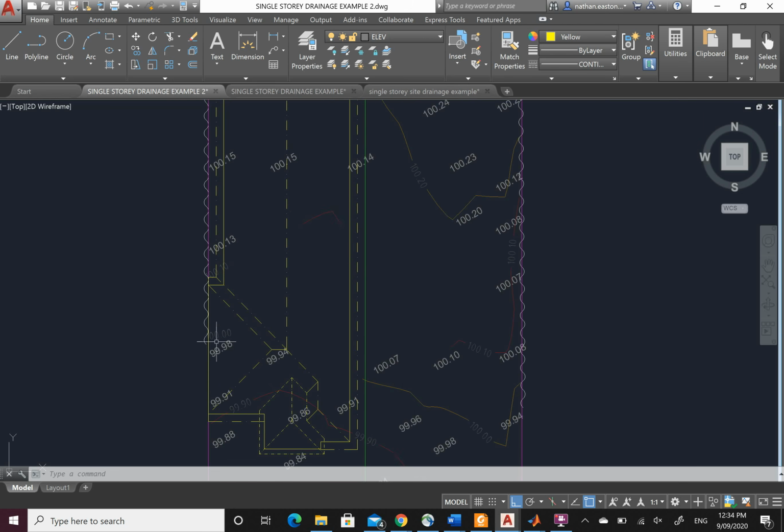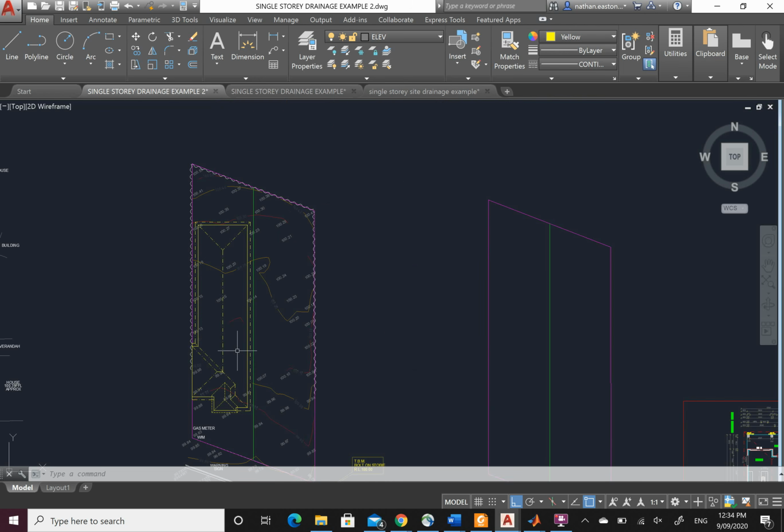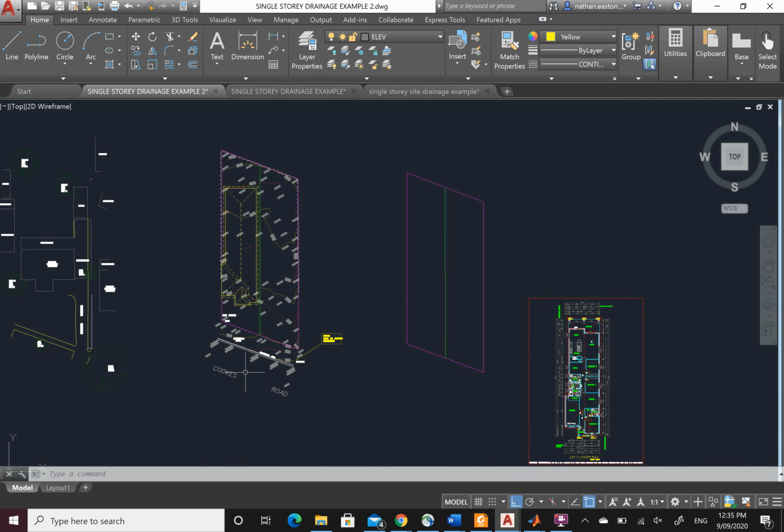We have a gutter, so looking at the roof, the water has two places it can land. It can either land on the roof of the house or it can land onto the ground. So what we're going to look at is the roof goes to a tank, from the tank goes to the street. From the ground, which is our runoff, goes straight to the street. They do not cross. So any water from the ground does not go to the tank, it goes straight to the street. All of the water, the discharge, runs out here and then down the road.